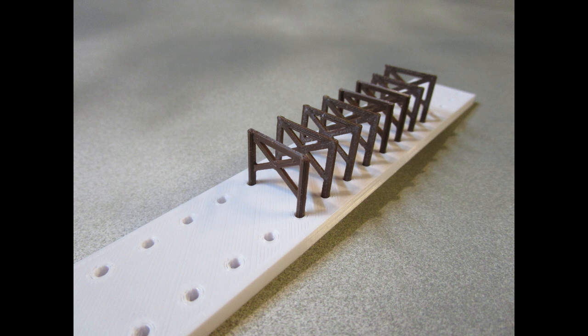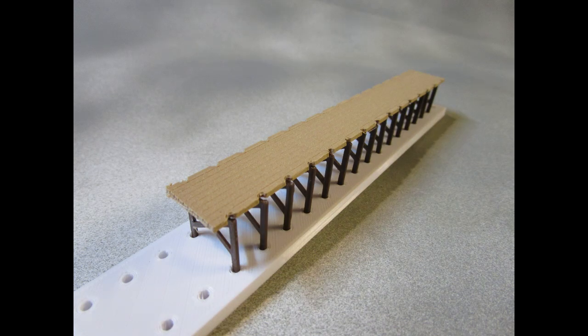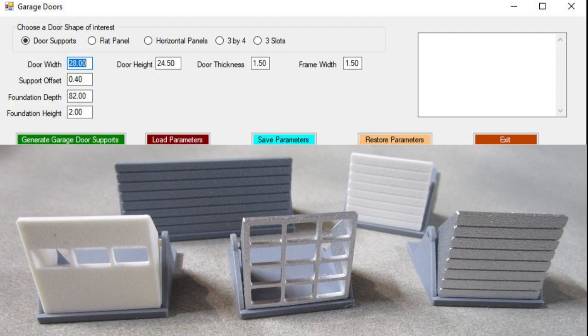While the fixture can be used directly, I decided to tape it to a piece of UHMW, ultra-high molecular weight polyethylene, and drill through the support tool to create my fixture. Why? To keep my fat fingers from gluing my supports to the fixture. UHMW is quite slippery and glue rarely sticks to it.